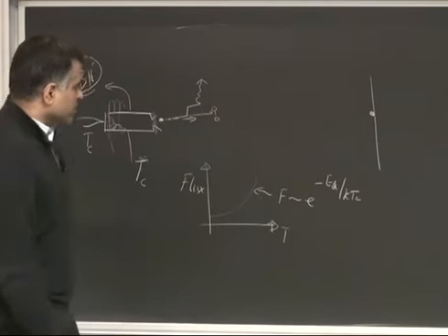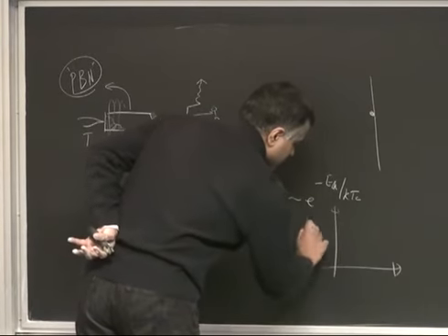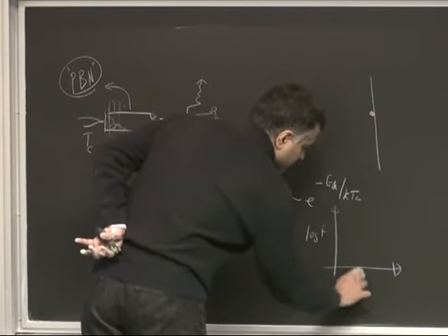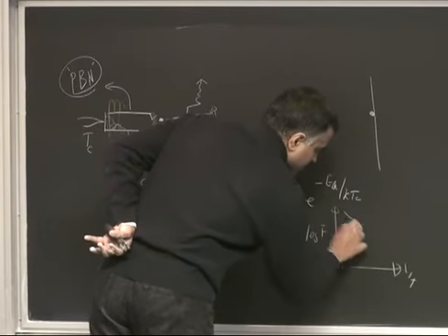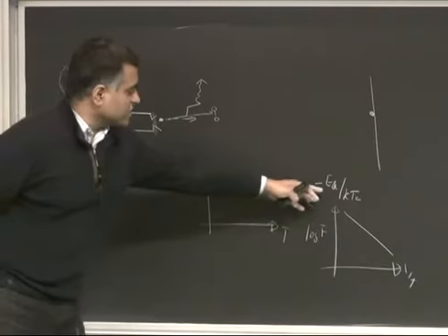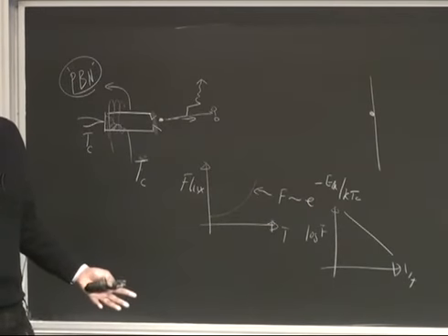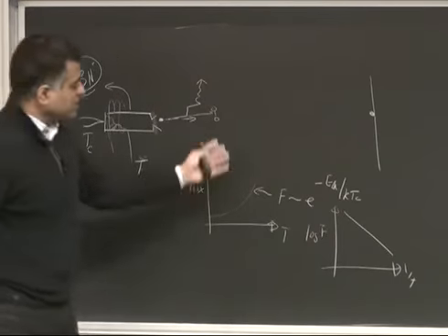So this gives you a very nice, and this is actually very accurate, meaning you can take a log scale plot of it, log of the flux, and plot it as 1 over temperature, and you will get a very nice line. And then these activation energies are typically of the order of a few electron volts, 2, 5 eV, something like that. That's how much it takes.